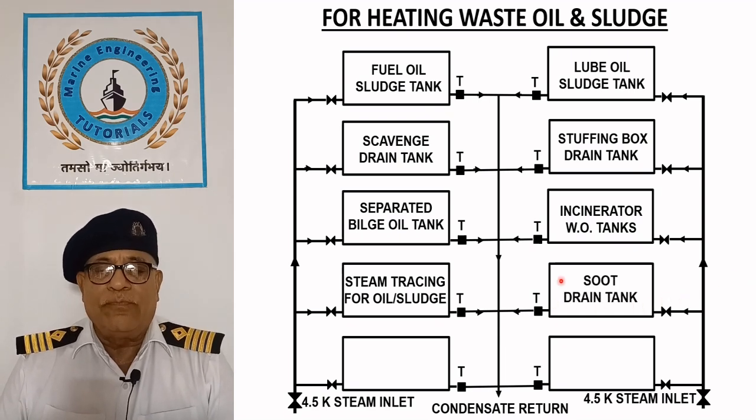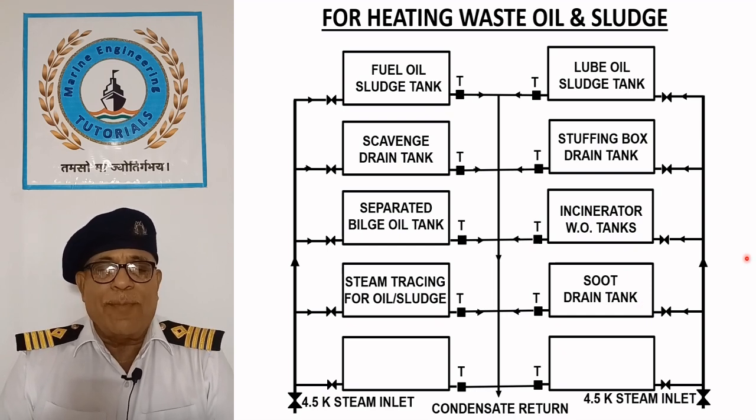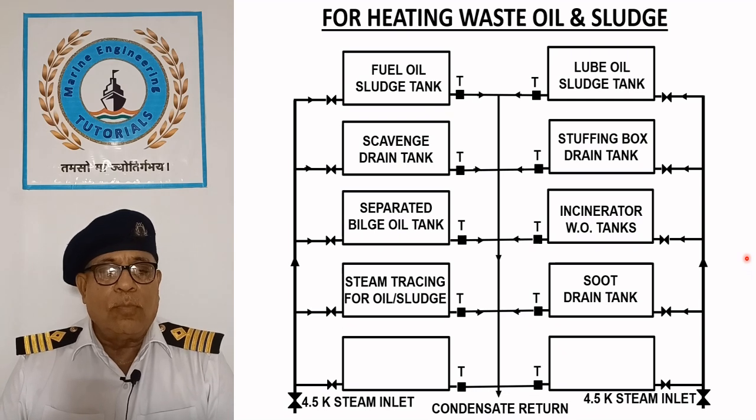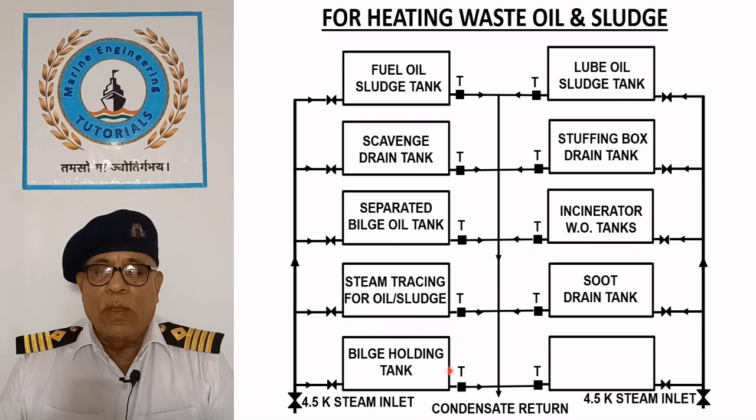Soot drain tank. Boiler washings and used chemicals collected in the soot drain tank are evaporated using steam to allow the safe disposal of soot ashore. Bilge holding tank.